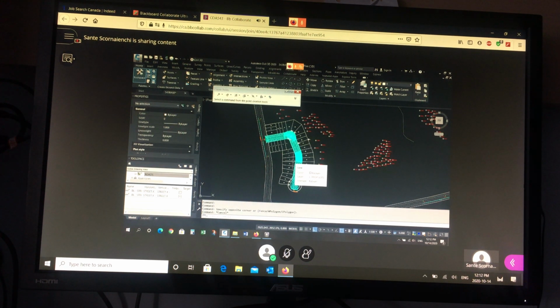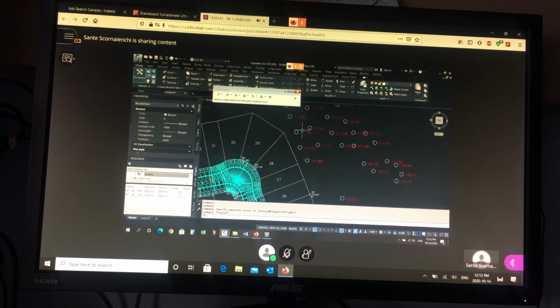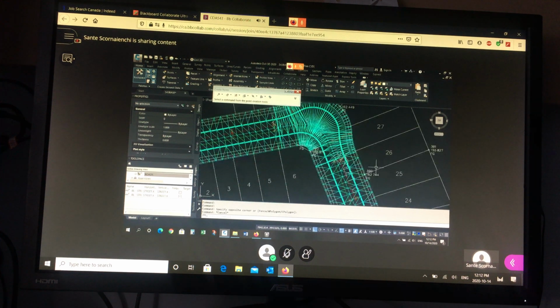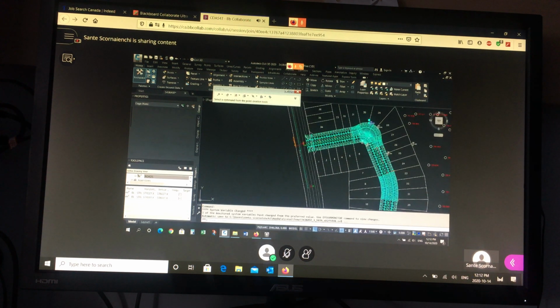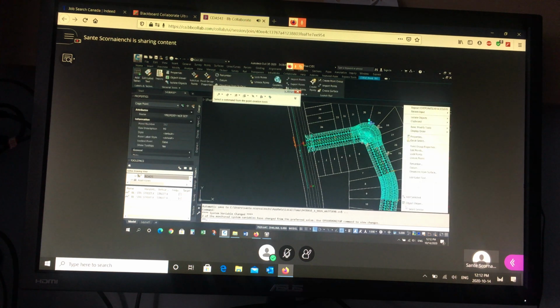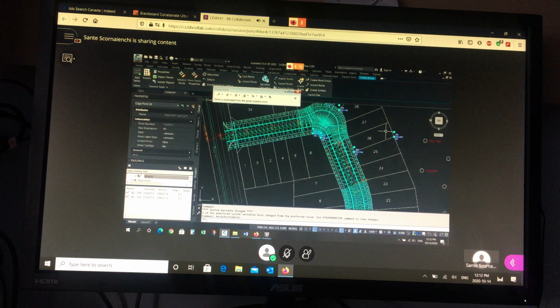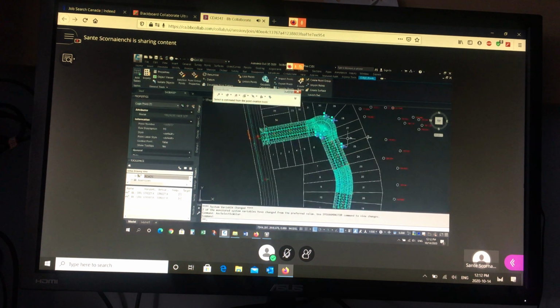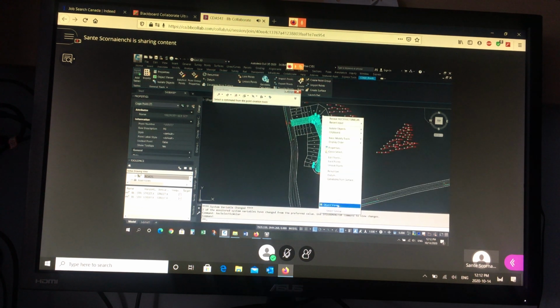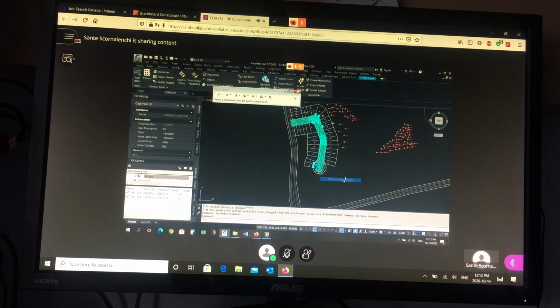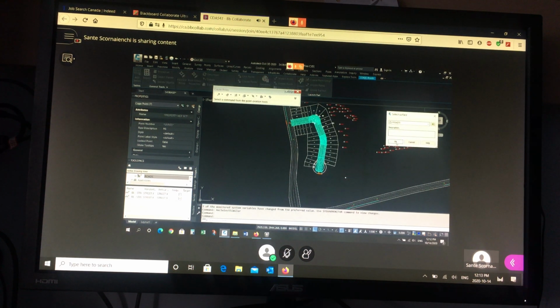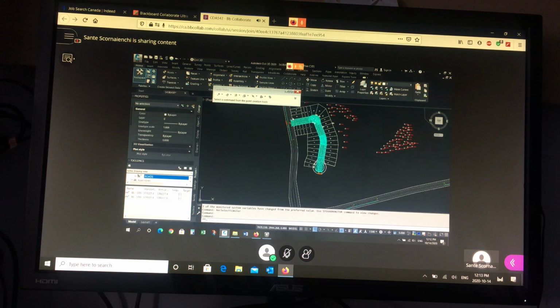Put points in everywhere, make sure they're on the right layer, make sure they're in the right group, create styles for each group, and then you can do more than one, right? I can click on 1, select similar, it'll pick all the points on that layer. It'll pick all the points on the front, that's one layer, this is wrong, this will be on a different layer, right? So you select all the front lot points, right click, select similar, and then elevation from surface, from the roads, boom, you get all the front lot corners for free on the entire site. That's what we're ultimately after.